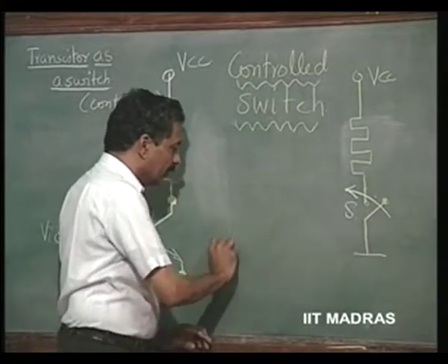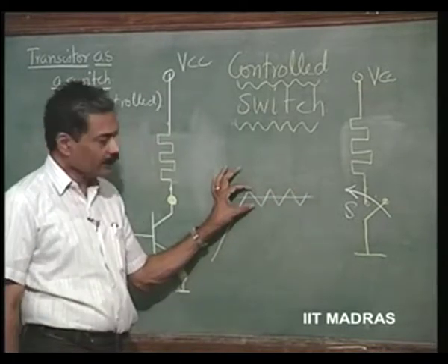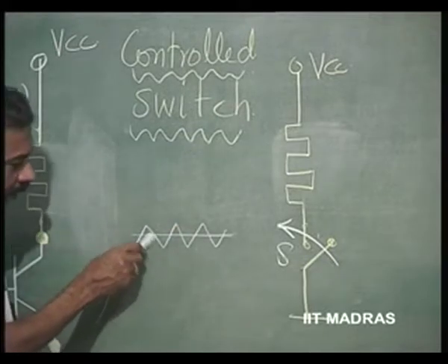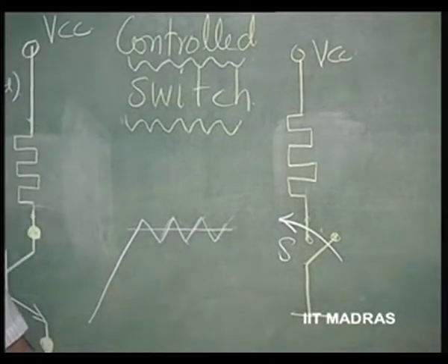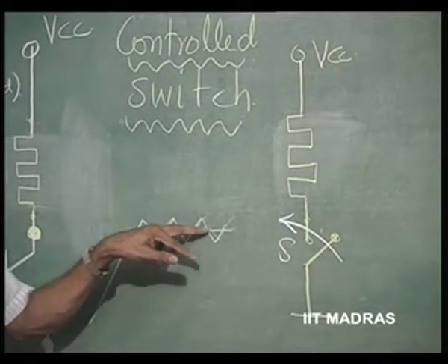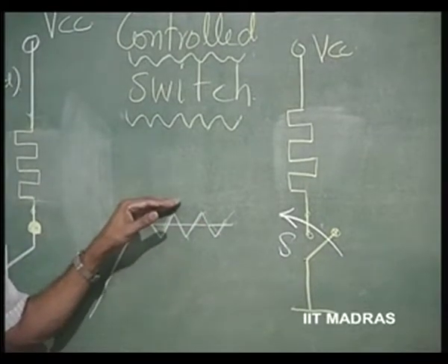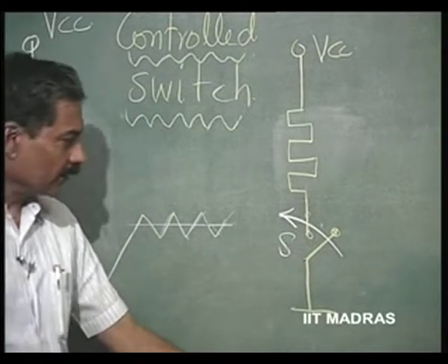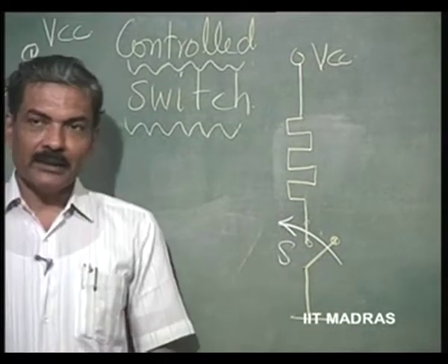This will normally remain at a sort of constant temperature, around a constant temperature, so that it is off on, off on, off on. So, such a controller is called an on-off controller, a very simple controller. Therefore, it is never going to reach the set point temperature ever. It will always fluctuate around the set point by a certain set magnitude. This can be adjusted. Such controllers require a control switch. A transistor can be used as a switch.